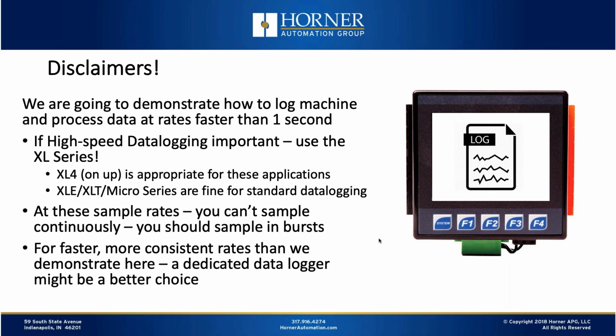Now, last disclaimer here, and that is if you're looking for samples every millisecond, like clockwork, and that's critical data, also consider a dedicated data logger. The OCS is extremely versatile. It does data logging really well, but it's also trying to control the machine or the process. And there's a lot of things it has to do besides data logging. So if data logging is the primary thing, and 1 millisecond type rates are absolutely critical, a dedicated data logger might be the way to go instead.